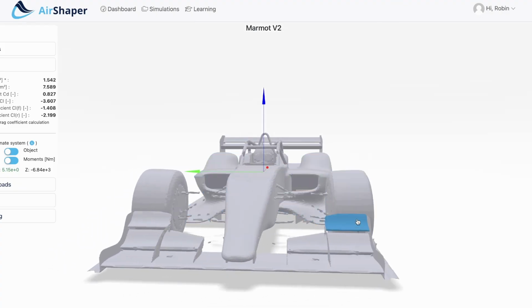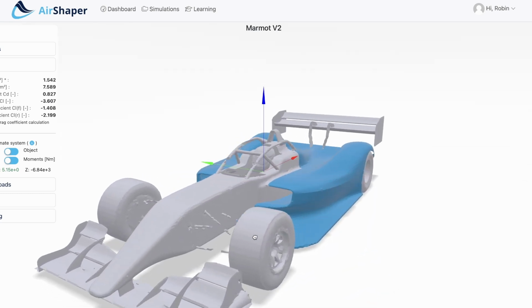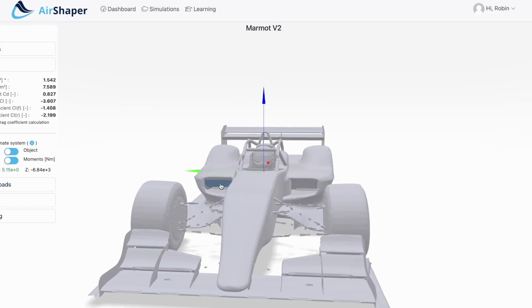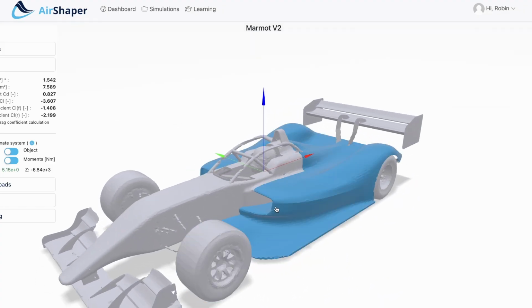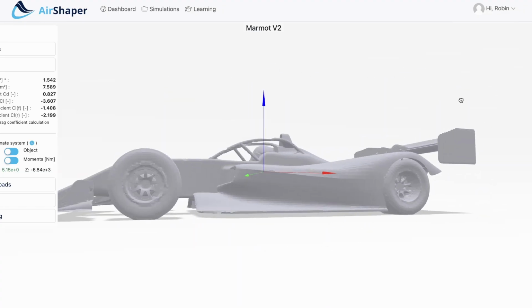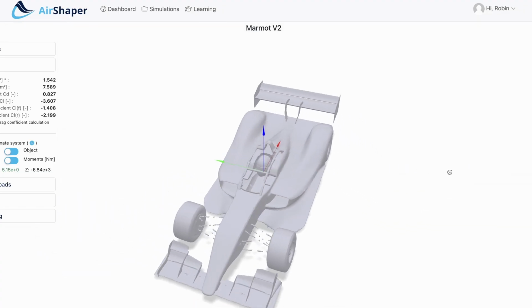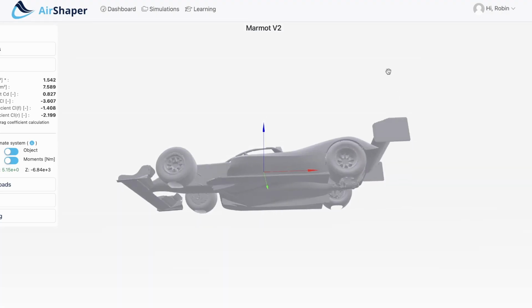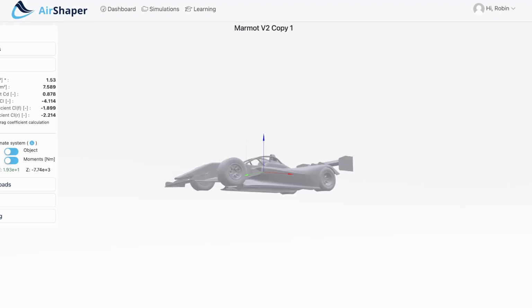Again, tweaking and refining the front wing, getting rid of the gurney flaps and shaping the flaps a bit better. That yielded a bit more efficiency. And here I was actually starting to develop the radiators a little more, and the radiator inlets had to open up a little bit as well. Again, with this basic rear wing, I know I can bolt bigger rear wings on and make lots more downforce if I needed to, but in this base setup, I wanted to keep it pretty efficient.